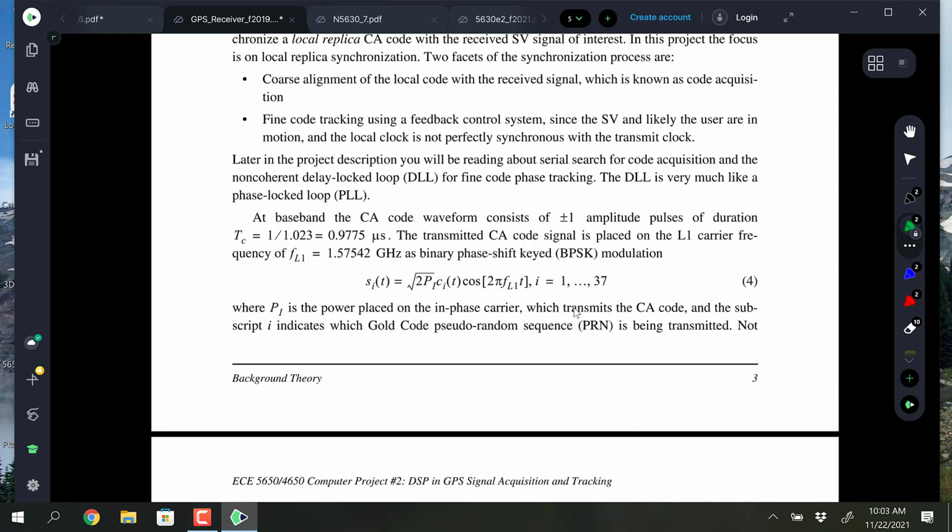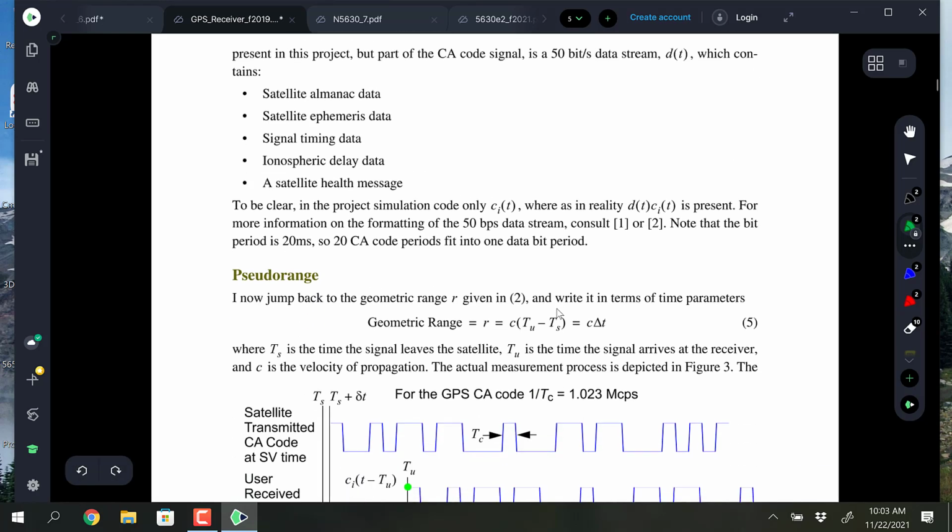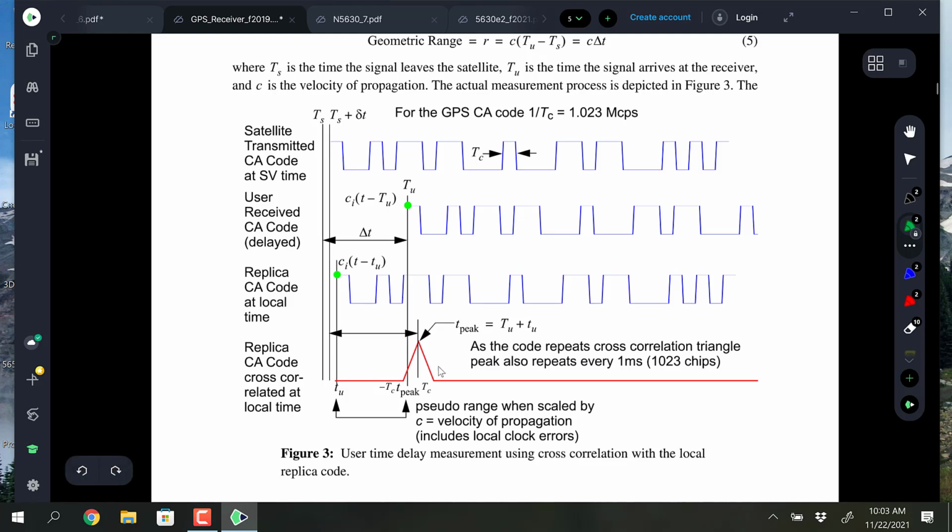I mean, you can find where the spreading codes are, because you know what spreading code is assigned to that satellite once you pull down the ephemeris data, and then you can lock on to the individual satellites faster. So the locking is what the spread spectrum receivers we were just talking about would be doing. There would be a CA code, which is the course acquisition code, which is 1023 chips long. Its chipping rate is 1.023 megachips per second. So it repeats every 1 millisecond on that code.